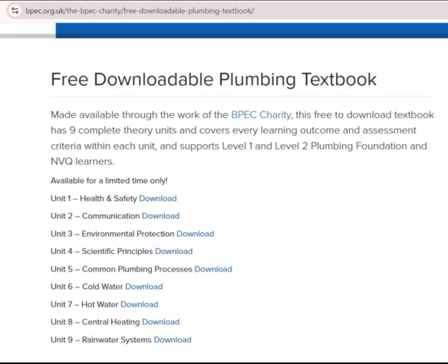Voltage, current and resistance in series and parallel circuits. There are two types of circuit: A. Series. B. Parallel. Series circuits. A series circuit has only one path from the power source through the circuit loads and back to the power source. In this instance, the current must flow through all of the loads.